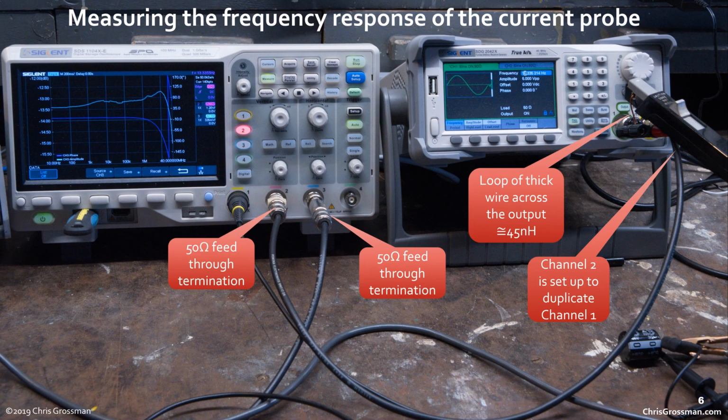So I'm doing a very simplistic measurement here. I've put a wire loop on the output of the function generator. I set channel 2 of the function generator up to duplicate channel 1, and that goes into a 50 ohm terminated input in the scope. And I plotted the response.